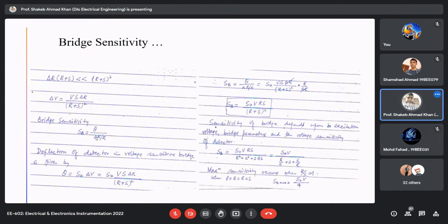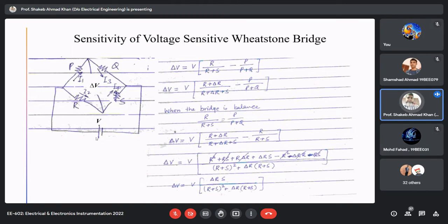How will you decide this excitation? So with the help of the rated current values of the resistances that we are using, we cannot apply a voltage more than that; only that much current they can carry. If we apply more voltage, then the current will exceed the resistance limit, and they will get damaged. Perfect.